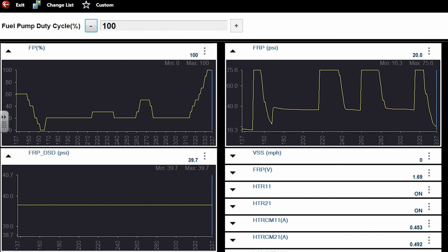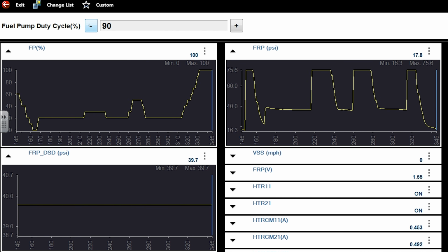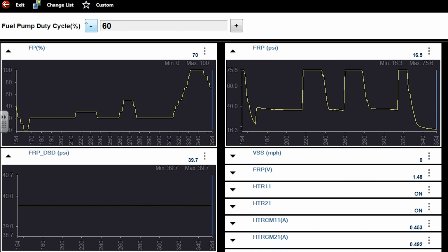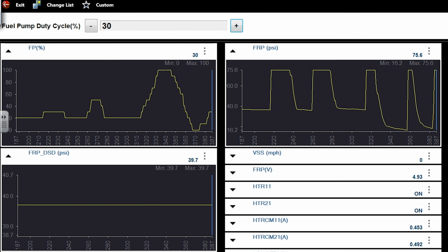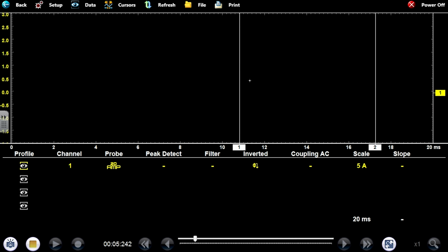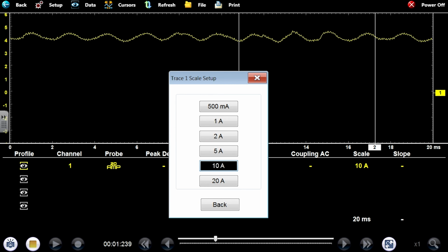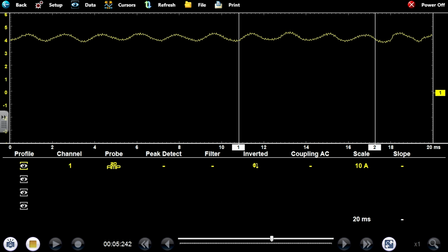When I go 100%, the pump just drops off. That's very weird. So I'm kind of forcing this pump to go max on me. There's 75. At 75, man, I should see a much higher amperage signal here. Am I? Yes, I am. Okay, cool. Sweet. There's 4 amps of current, 4.5, right? That's a pretty standard looking pump pattern right there.